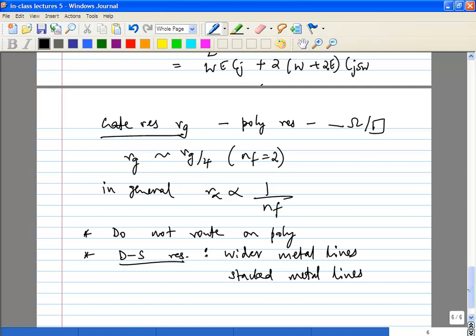It may not be the thing which is really limiting your performance, and typically for most mixed signal designs, you may not worry too much about this capacitor. But there are certain cases, definitely RF cases, where you would worry about it, and some important cases where you have to be careful. If you're building a high speed ADC or something, you really have to be careful about these things.